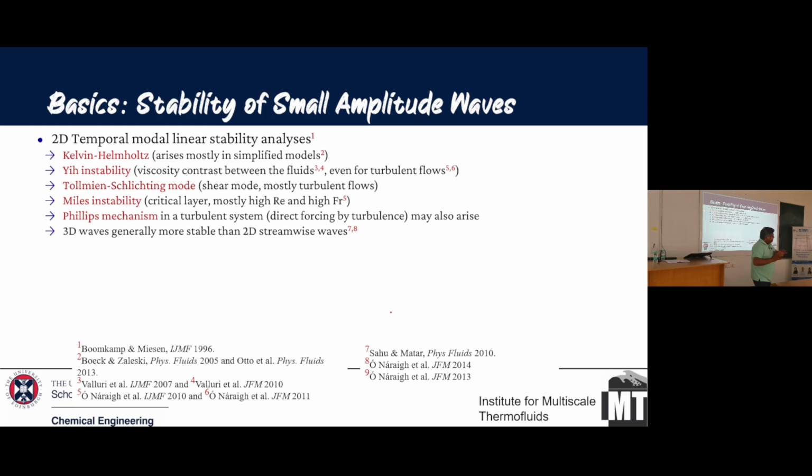Turbulence itself indicates these pressure pulses. Okay, and that can also come up. Obviously the pictures which I showed were 2D, but you will also have 3D instabilities. Whenever you have a wave, you can have a wave which is growing at the same time, but this will develop a tongue, but this won't develop a tongue. So you can have a three-dimensional instability as well.